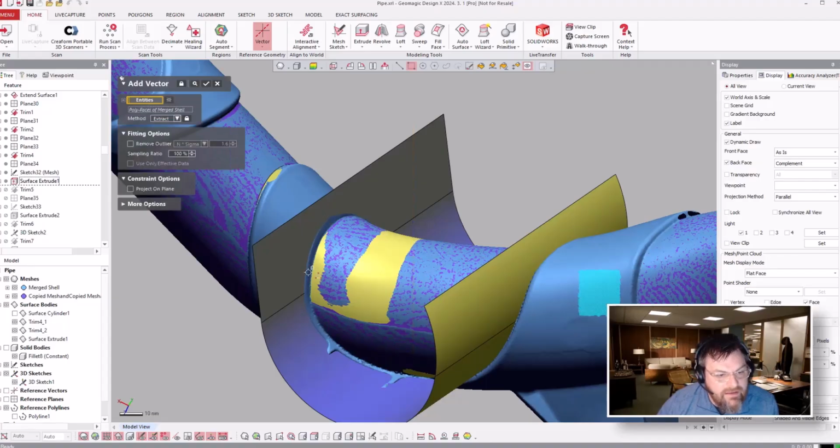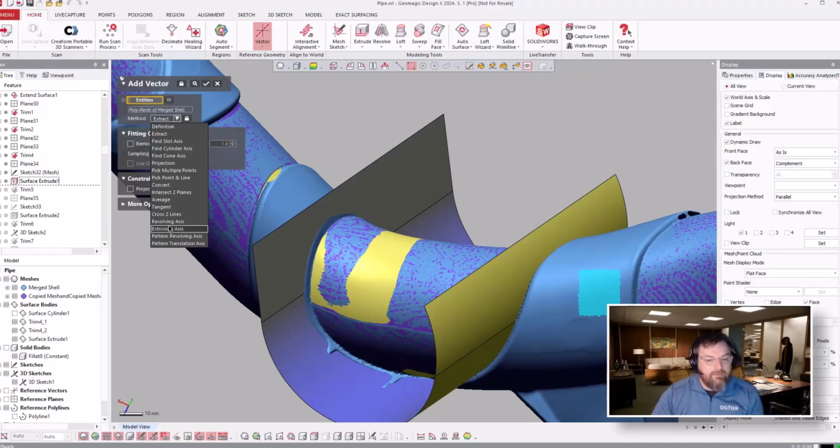So you can select the edge of this all the way around, and you can say, I want to extract the extrusion axis. If you select a bunch of geometry, it will try to find that silhouette profile of it and give you that axis, and then you can put a plane on it, and from there create a point in a plane and create an extrusion direction like this